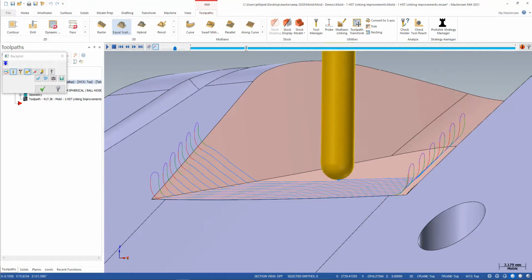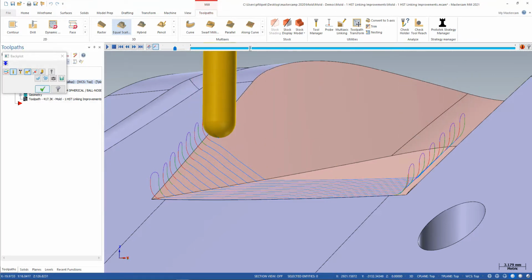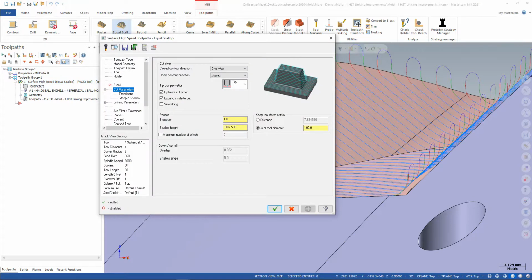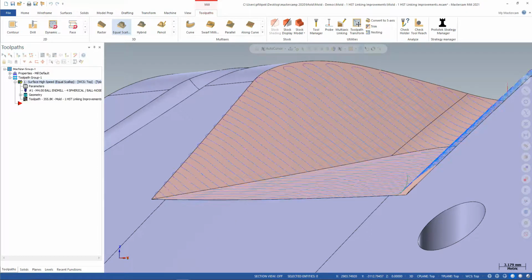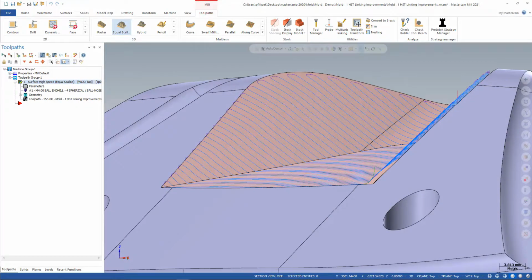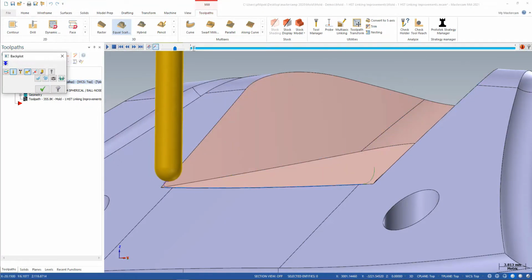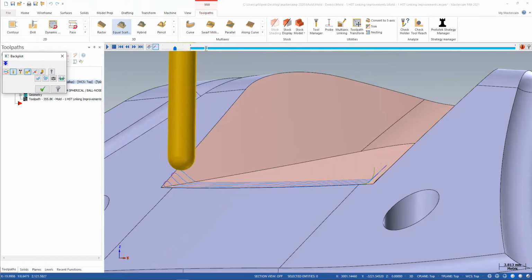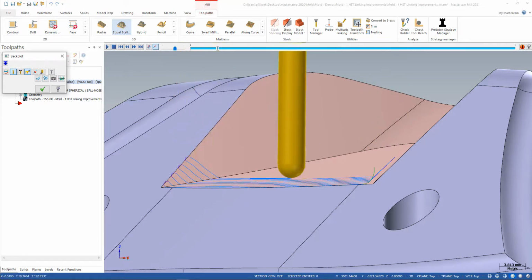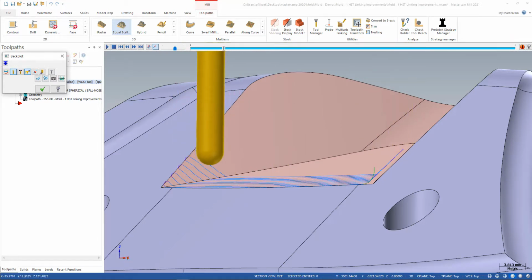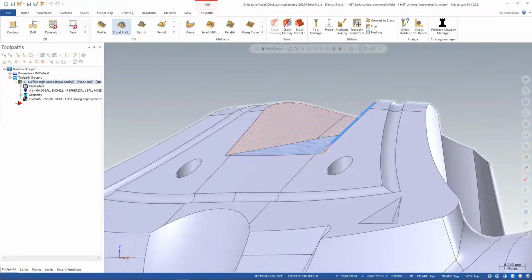So this is definitely a nice move, is to apply transitions. You know, if I take that apply transitions off just to see, we'll regenerate that. Now see how our transitions are on the part again. So we're going to be seeing them moves on all the edges, or maybe that's creating some havoc with us with deburring or with polishing more than anything probably. If we can't have them little moves up on top, maybe that's an issue for you guys' situation back at the shop.